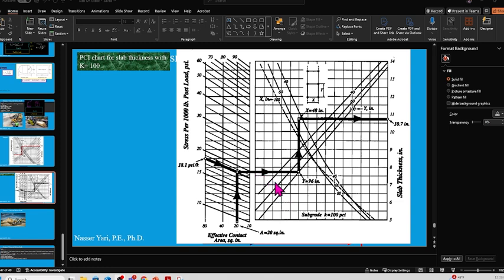meet these 3 lines. And remember I showed you we had the X and Y dimension on a rack, and that's the Y dimension, which was 8 feet, becomes 96 inches. Then from here, you're going to meet this line, which is the X dimension of that rack in inches. Ours was 4 feet, and that's 48 inches. Meet right there. Then you go across, and it comes out to 10.7 inches. That's pretty easy. And you'd probably be skeptical and say, no, this is just a chart, I don't see an equation. But believe it or not, a lot of slabs have been designed this way for many years, and they still stand in good shape.